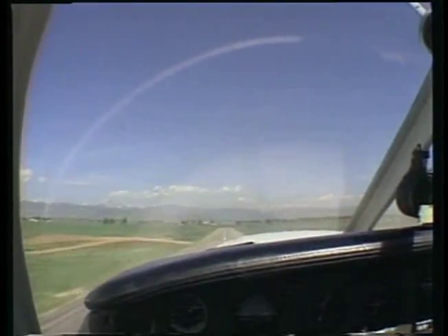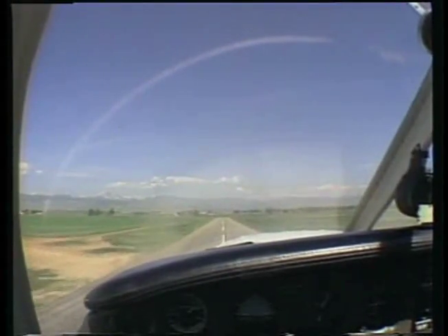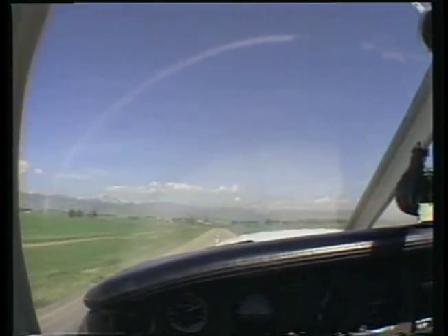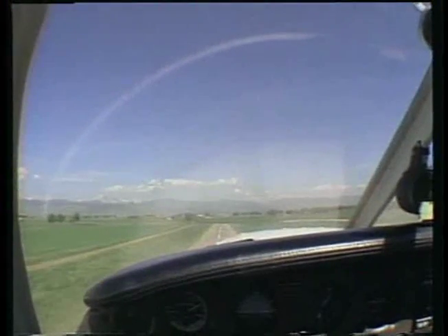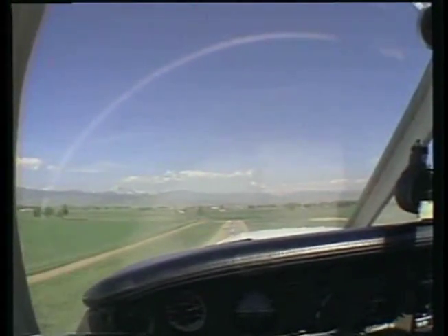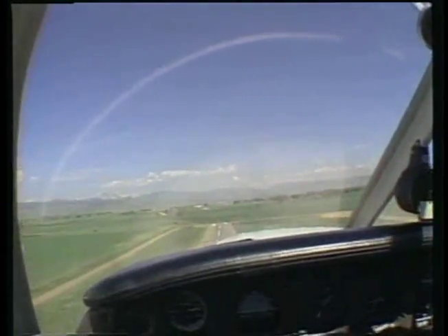As you lift off the runway, lower the pitch attitude and accelerate in ground effect to the best angle of climb airspeed before initiating a climb out. When all obstacles have been cleared, accelerate to the best rate of climb airspeed. Slowly retract the flaps and continue your climb.